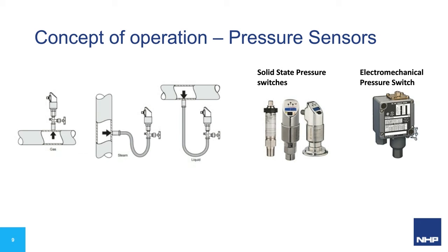Now, the advantages of using pressure switches, you get to directly monitor the pressure in your system, and they're fairly simple to install and use. Disadvantages, however, are that chemicals may not be suitable for the bellows type that you have, and you can't take a one-size-fits-all approach. You need to ensure the pressure range of the tank is detectable by your pressure switch, and it's not too much for your switch as well.